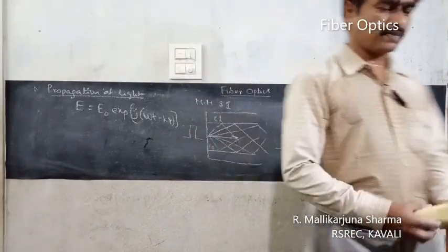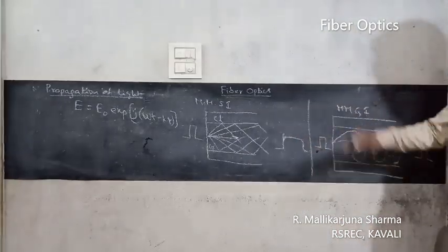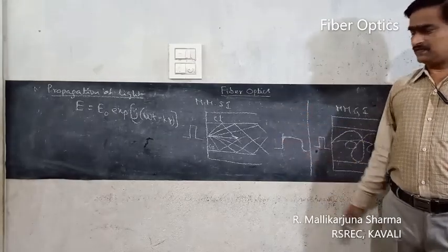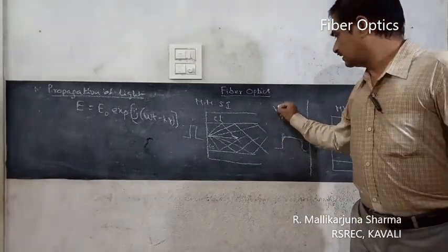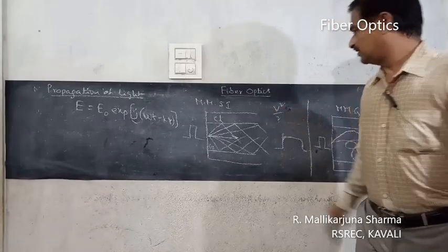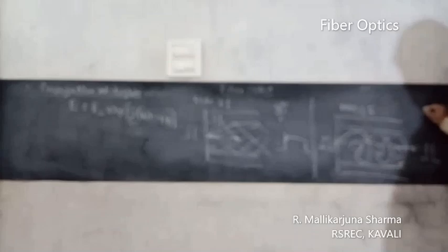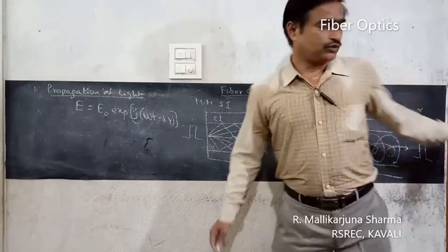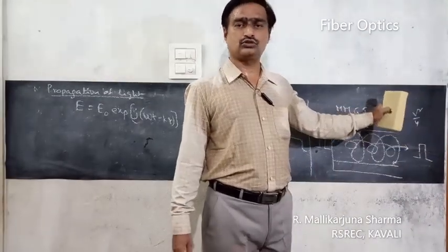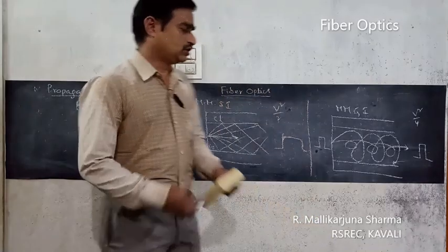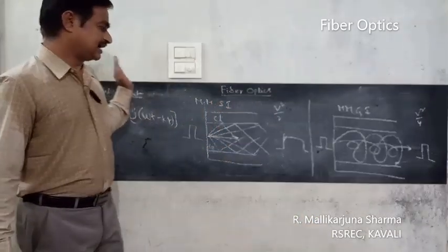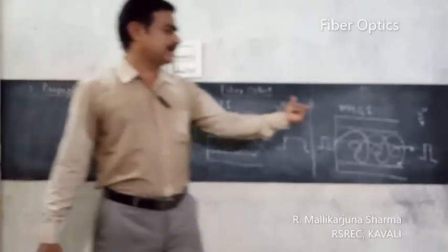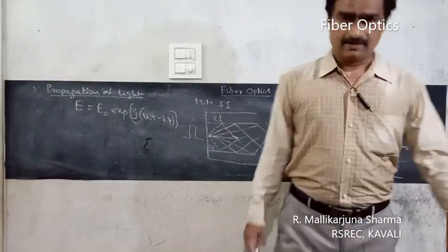Then coming to modes of propagation through these types of material, in the next few minutes we are going to have a parameter called the V number. With the help of that V number, the number of modes is given by V square by 2 here. Here V square by 4. Because as the structures are symmetric, we have fewer modes of propagation through this one. This is how the propagation of light waves takes place in multimode step index optical fiber and multimode graded index optical fiber.